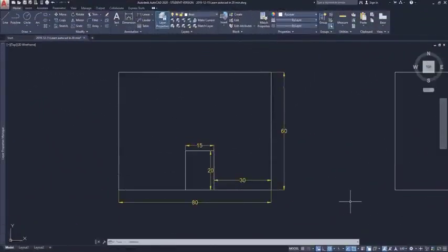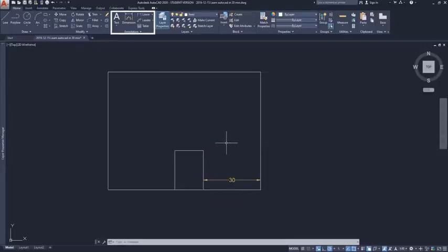Part 6. The final part. Dimension lines. Now I am going to teach you how to draw dimension lines. This is a classic feature for annotation in your drawings. In this figure, you can see the dimension lines indicating its distances. Now, to draw dimension lines, there is a panel on the Home tab here.